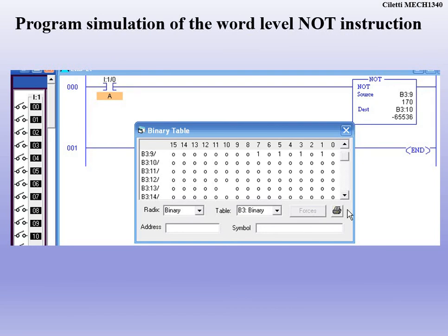So what have we learned in this chapter? We learned about ANDs, ORs, inverters, NANDs, NORs, and exclusive ORs. We learned what those logic gates look like and how we implement them. And then how we can create a Boolean expression from those logic gates, and how those logic gates translate to our ladder logic, understanding that ANDs are series, ORs are parallel, and we can do combination logic, creating ANDs and ORs and inverters and all those different things to create our scenarios.